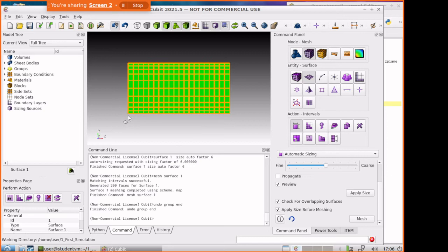So for example, with triangles, or in 3D with tetrahedrons, it might be easier to mesh it in an unstructured way, but the quality of your simulation is decreasing with an unstructured mesh. So a mesh looking really neatly structured like this one will always deliver better and faster results than an unstructured mesh.